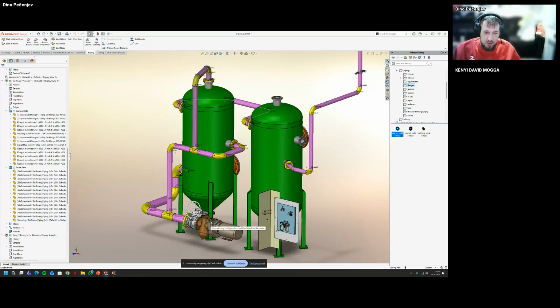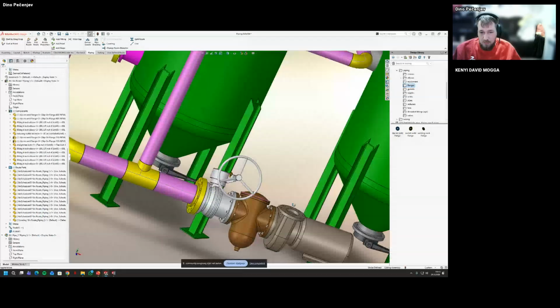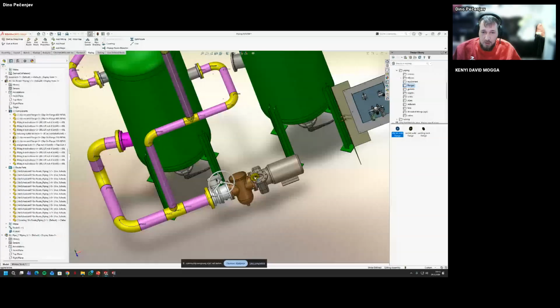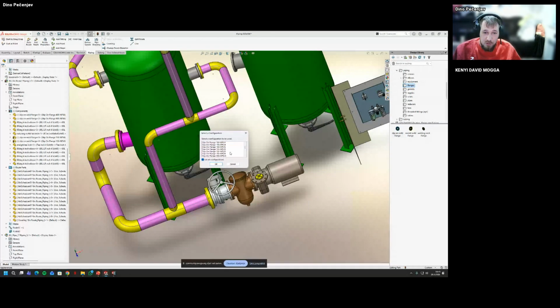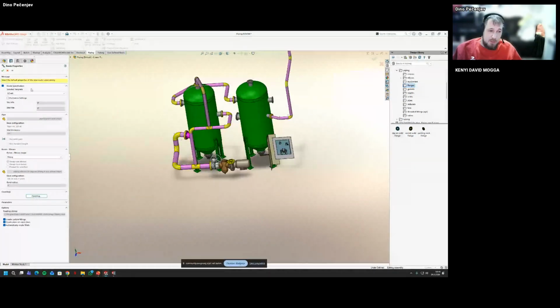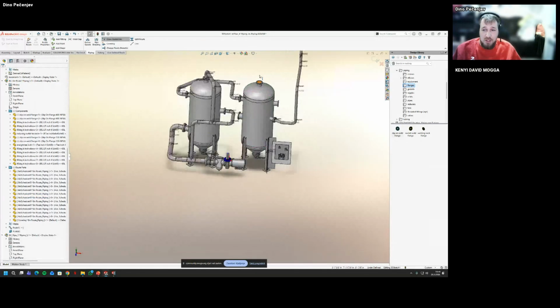I mentioned split route. So we've done manual automatic splitting with the T's, but what if we want to have more control over it? So it would be a slip on weld flange. I'm just going to go here and select 150 or 400, simply NPS 4 for this part. And we're going to use a specification template because we have all the settings we need, and we're using the same template we created at the start.